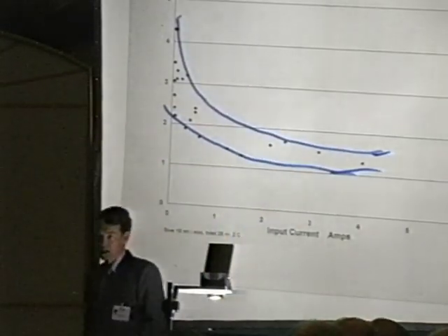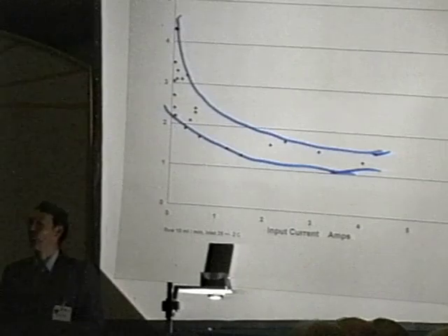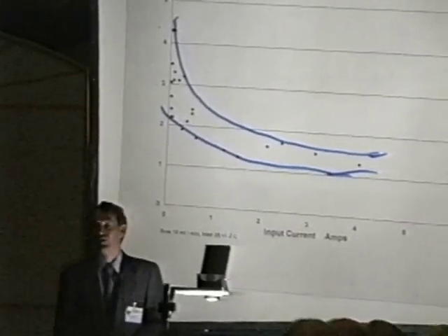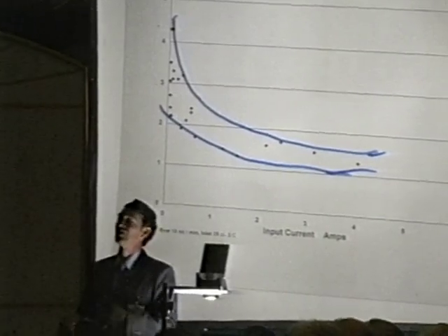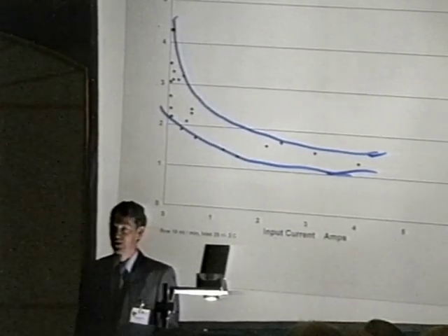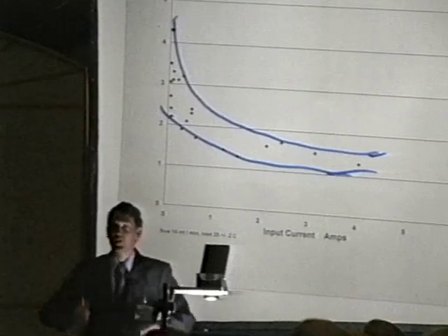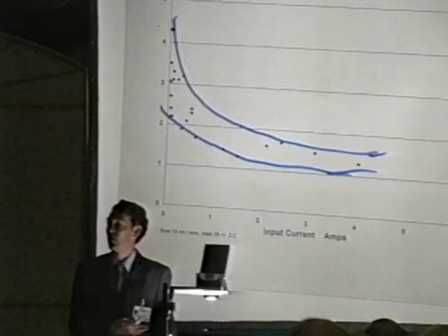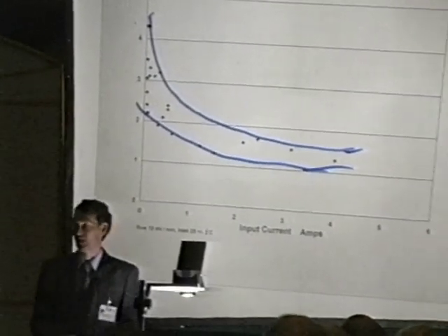It took me a long time to come to grips with believing the low values, and I would advise someone doing this to, before you totally dismiss it, play with it and make sure that your thermocouples are reading their real values, and know what your error bars are.